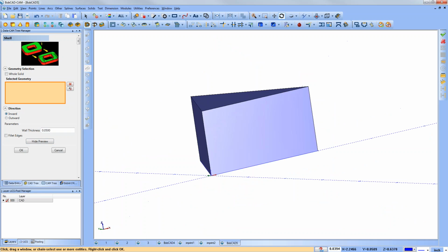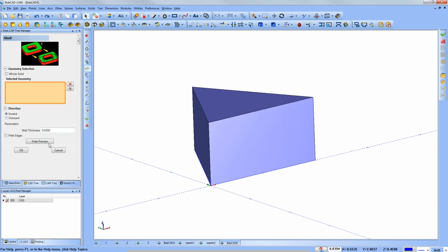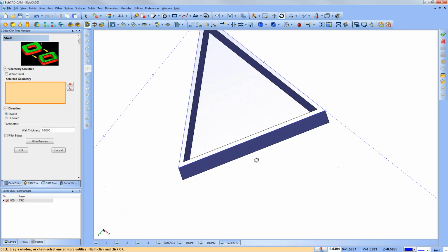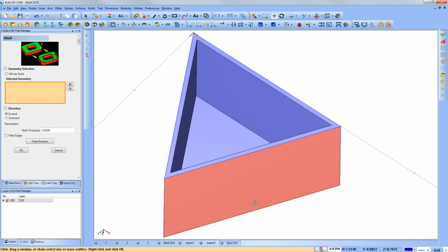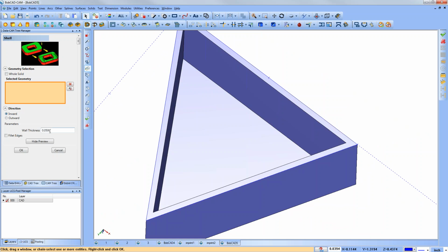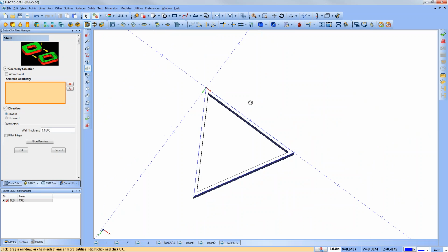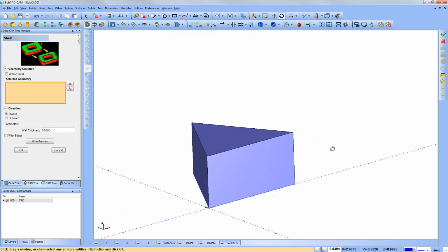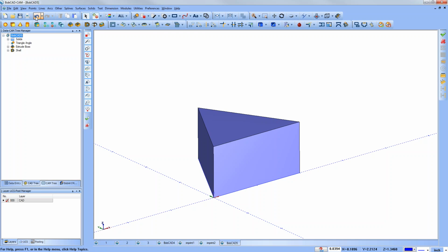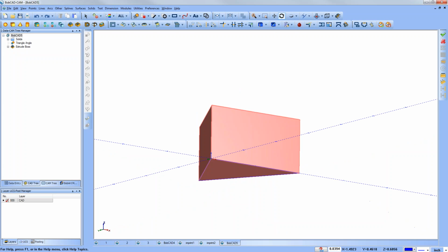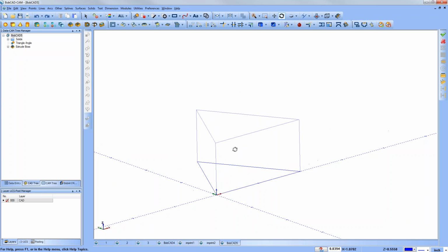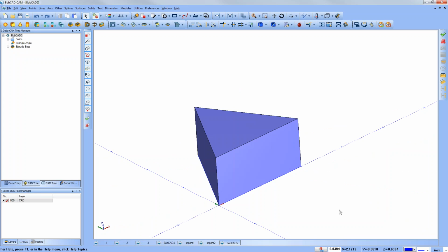Let's select 2. Give me one second here. There we go. Okay, so there we see an example of how it left 0.05 wall thickness. I just picked the one surface. If I want the whole solid, let me show you the difference. Let me cancel out of it. Back up. Right, we got our solid piece. If I press S for shading, it just gives me a wireframe. There's no thickness to it.